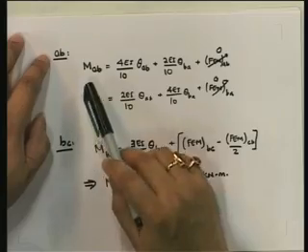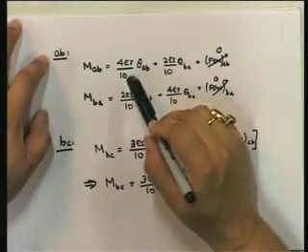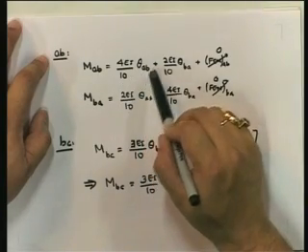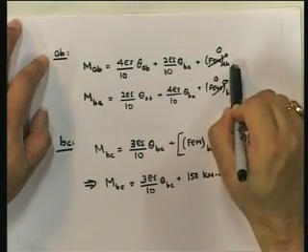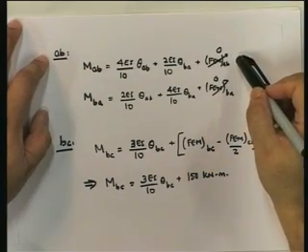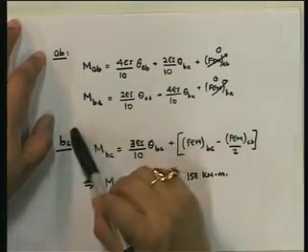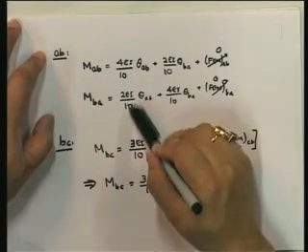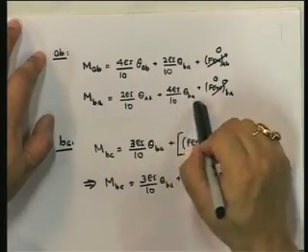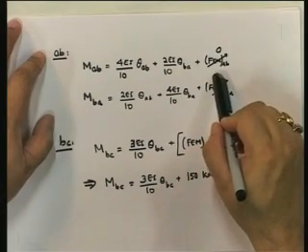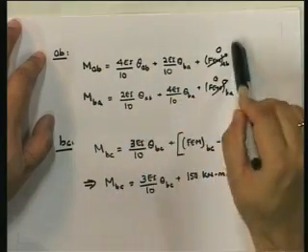Okay. So, having identified the 2 degrees of freedom, the first step is to write down the member force deformation relationships. So, we look at the member force, and AB is a fixed member. So, MAB is equal to 4EI upon L theta AB plus 2EI upon L theta BA plus the fixed end moment at AB, where L is equal to 10. Now, since there is no load in member AB, obviously the fixed end moment is 0. Okay. Then MBA is equal to 2EI by 10 theta AB plus 4EI by 10 theta BA plus the fixed end moment at BA, which is also equal to 0. Okay. So, that is the member force relationship for MBA.